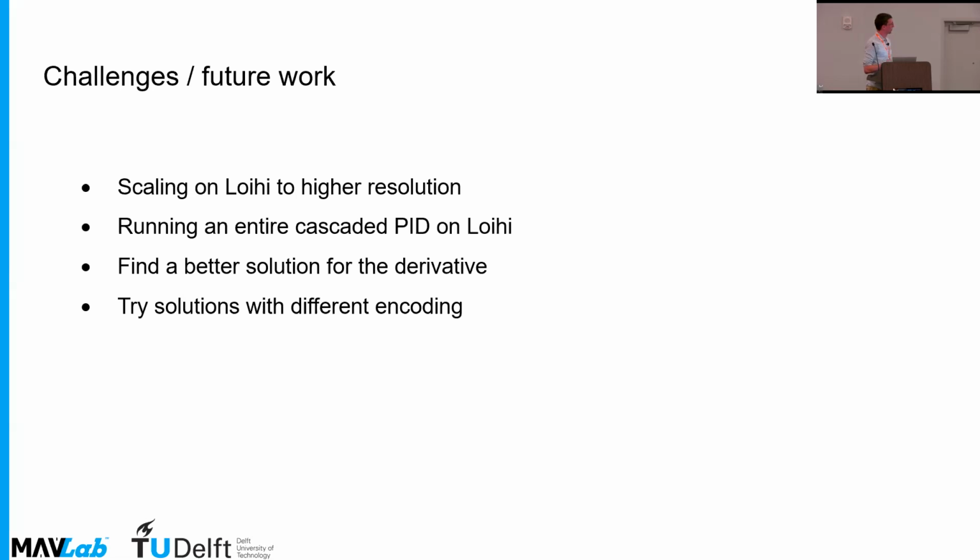And one big challenge that we had here is that the derivative that's calculated right now is a one-time step derivative, which means that if you have a short time step and a low resolution in neurons, a shift in the bins of the population coded neurons will result in a very high derivative at this one time step, and it will result in a zero derivative all the other time steps. So this requires, for instance, increasing the resolution of the neurons to a very large value, because if the resolution is infinite, of course, then the derivative will be perfect as well. But there are some limitations, of course, to the hardware that we have.